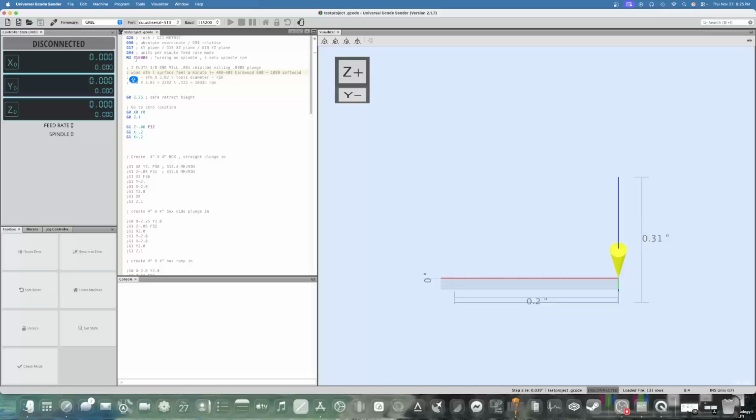Like I said, I'm using 18,000 RPM, 1,000th chip load, 2-flute end mill. So that would be 36 inches per minute or 914.4 millimeters a minute straight running. Now, if that was a 4-flute, that would be 72, or a little over 1,800 millimeters a minute. If that was a single flute, then that'd be 18 and a little over 450 millimeters a minute. So any one of those variables change, the inches per minute or millimeters a minute will change, and often drastically. So that's why you shouldn't give that for an example in these groups.